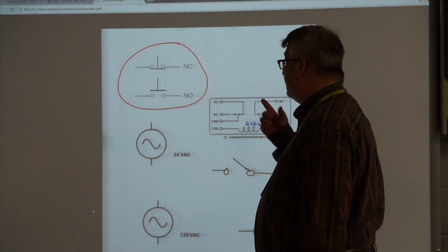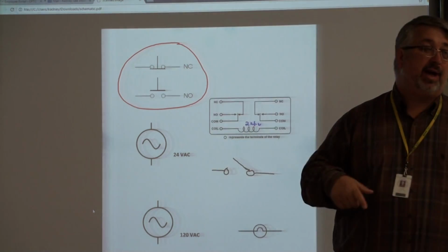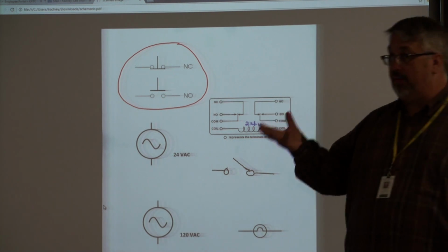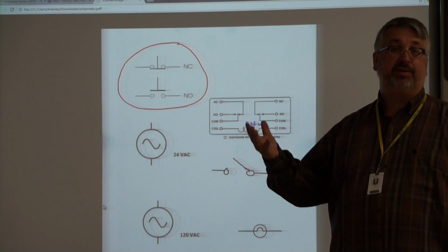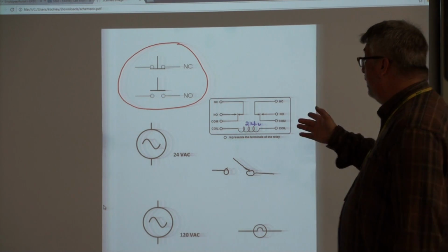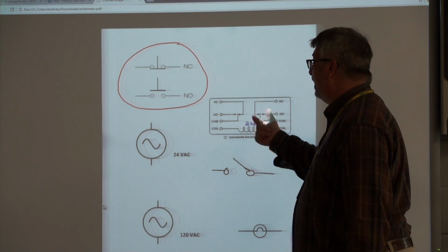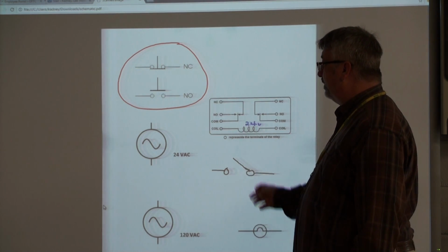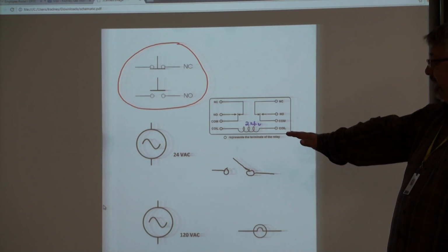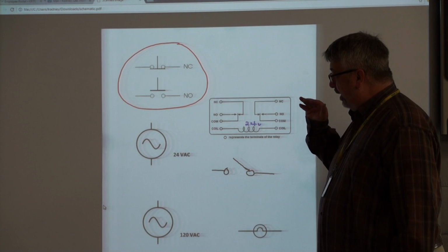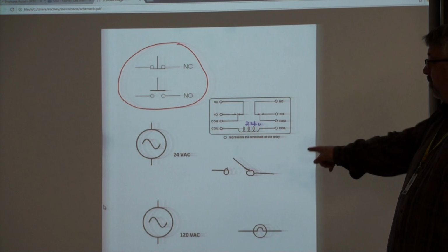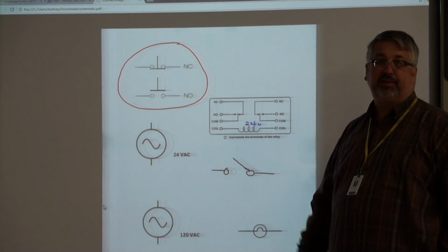Plus, you have to make sure that the contacts are capable of handling the voltage. Not only the range, but the type, because there is a difference in the AC and DC contacts on these things. So this one can handle 24 volts AC, what's supposed to engage the coil. The contacts themselves can handle this 120 volts. So we're going to start with the basics of wiring the coil. So what do I need to wire the coil using this toggle switch I've got here?